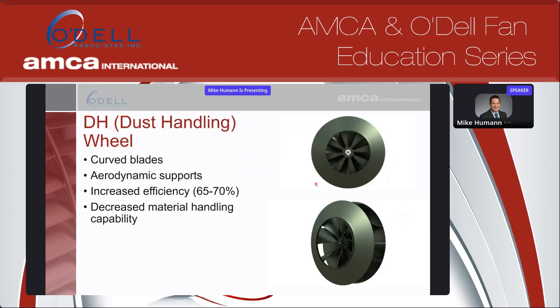So this is still a radial style wheel. These are a little bit more efficient. You'll see that the blades still radiate out from the middle, but there is a curve to them and a little bit of a cup. These wheels are more efficient than just the straight radial blade. You'll see that we have increased efficiencies from 65 to 70%. So we're already up 10 to 15% on that straight radial wheel.